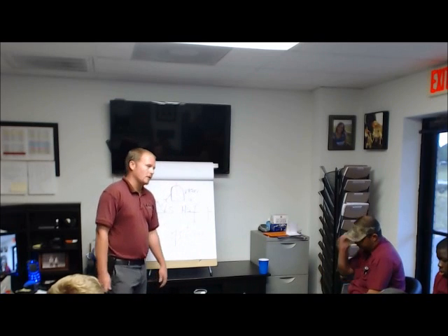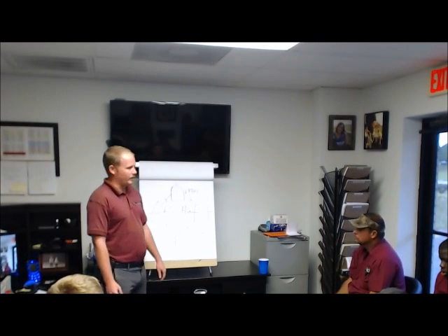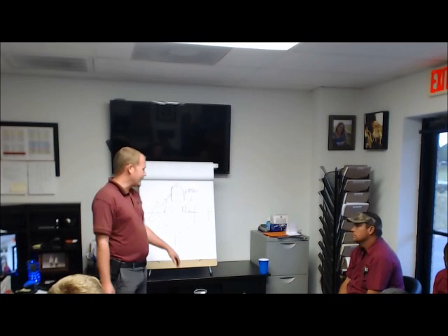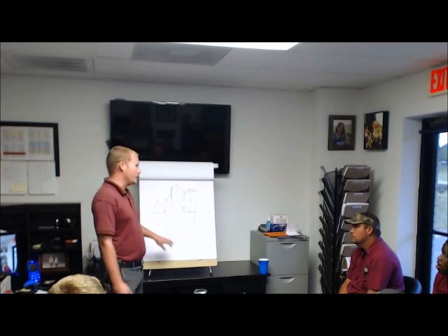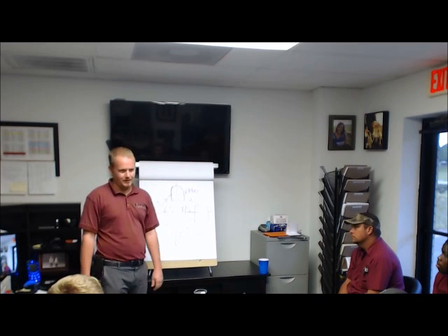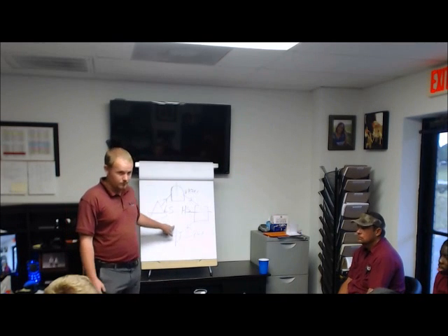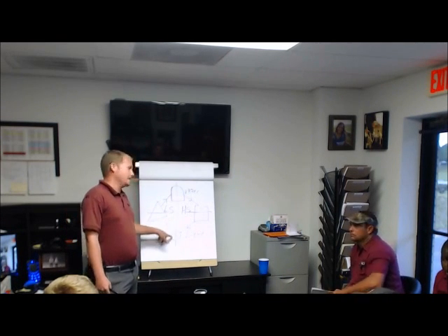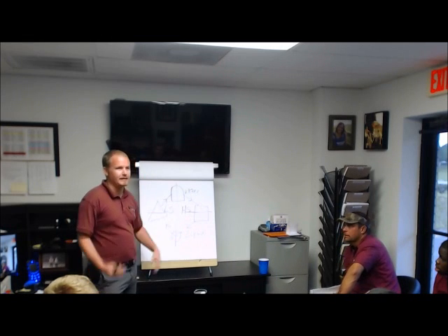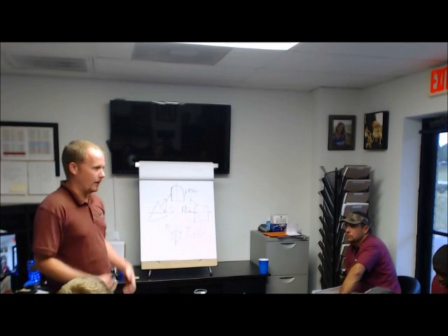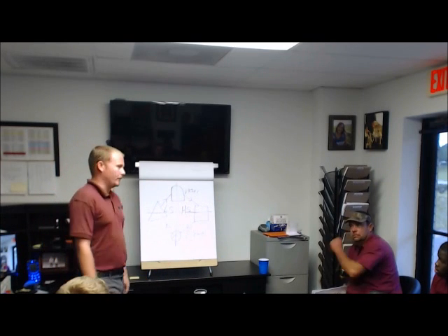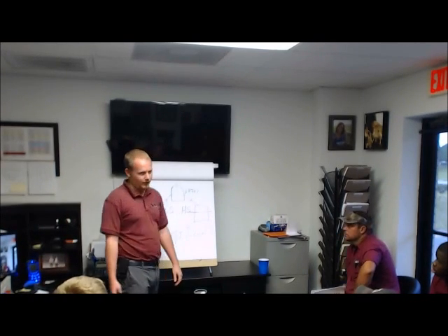Okay? All right, so let's say that we are working on a ductless system and we can actually read the pressure and temperature on the expansion line. What do we want to actually see is going on in this expansion line? We want to see a mix of liquid and vapor. Exactly, because you want to see that flash gas. It's in the process of changing. We call that boiling practically. In our world, we see boiling. You can call it flash gas, you can call it mixed vapor and liquid, whatever you want to call it.